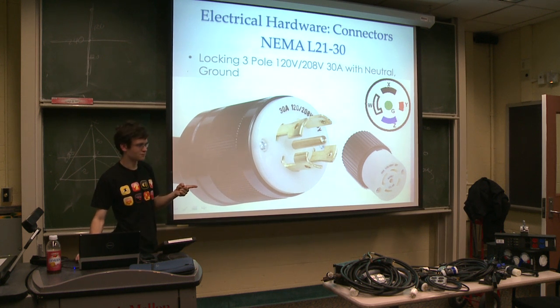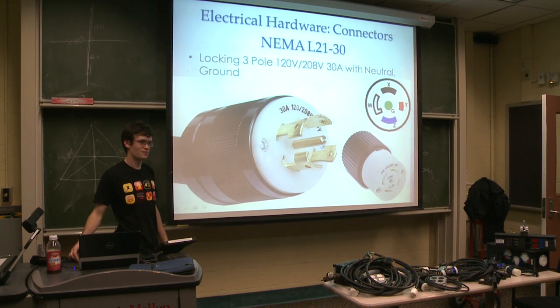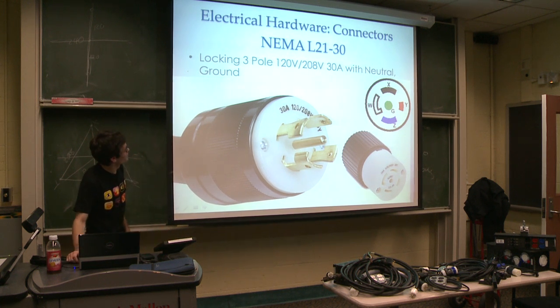Hey man, why was that cable that we had at the Guster concert, that was Camlock into an L21-30 plug, bad? Depends what the Camlock was rated for, but it was probably more than the 21-30, or more than 30 amps.